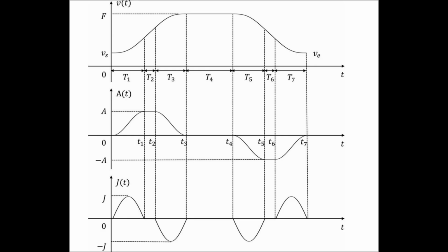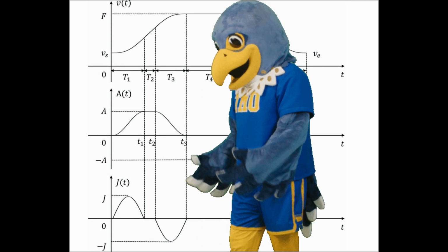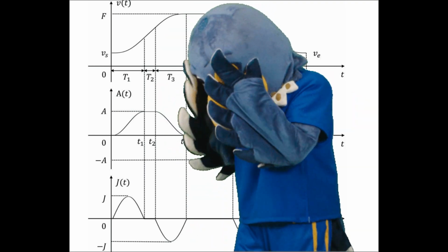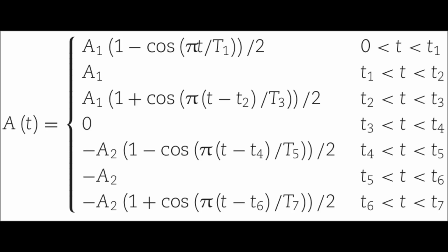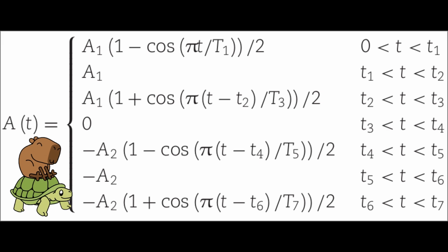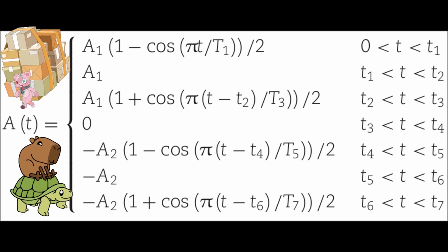Second, we have the trigonometric jerk profile. As you can see on the graph, the changes in acceleration are completely smooth and curved. No more infinite jerk. However, this method has two massive flaws for our project. Because trigonometric functions are naturally slow at the start and end, this algorithm is not time optimal, extending our total travel time significantly. Also, calculating continuous sine waves creates a very heavy processing load for a simple microcontroller.